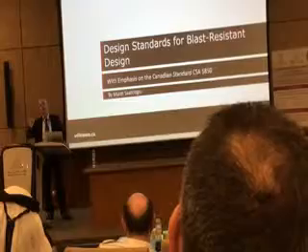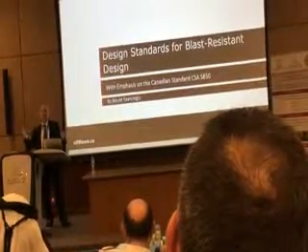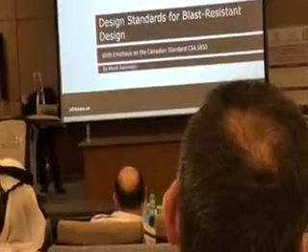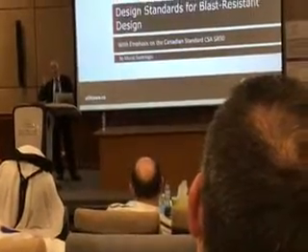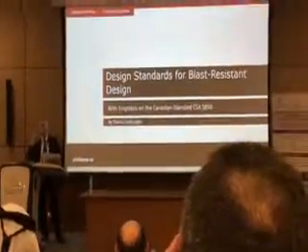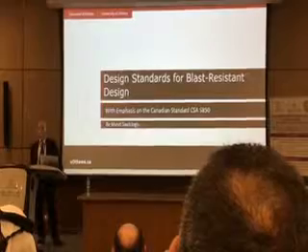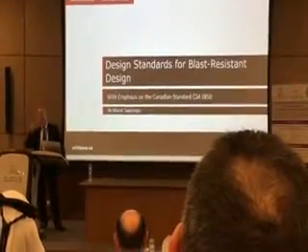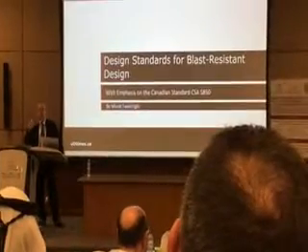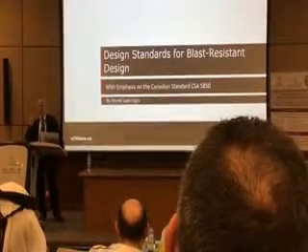So if you have a building within that 5 meters, then it hasn't fully formed, and you're in that excessive heat, excessive pressure zone. It starts causing material failure. I have a slide to show, it starts scabbing and spalling the concrete. The effect on material is more intense than the effect on the member. This is called close-in explosions.